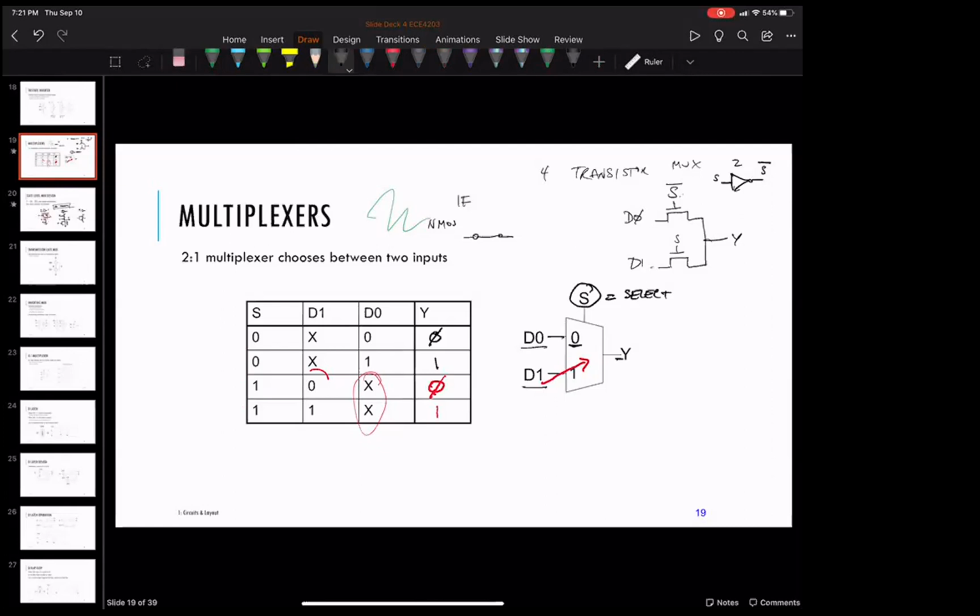So with just these 4 transistors, including what's in the inverter, I would be replacing 20 transistors worth of stuff. So it is attractive, so sometimes we don't use the whole pull-up, pull-down network in certain types of circuits.